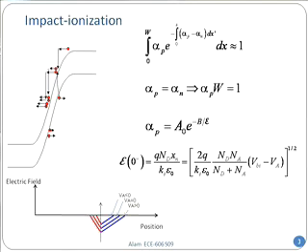Electric field, as I have already told you, this is a formula that we have derived already, right? Do you remember that VBI minus VA, and it's reverse bias? So this should be a plus sign, VBI plus magnitude of VA. And then from this, if we insert back in the equation for alpha p and require that condition, alpha p multiplied by W equals 1, be satisfied, the only thing unknown in that equation is the applied voltage. And as a result, I can immediately tell you at what point this diode is going to break down by avalanche multiplication.